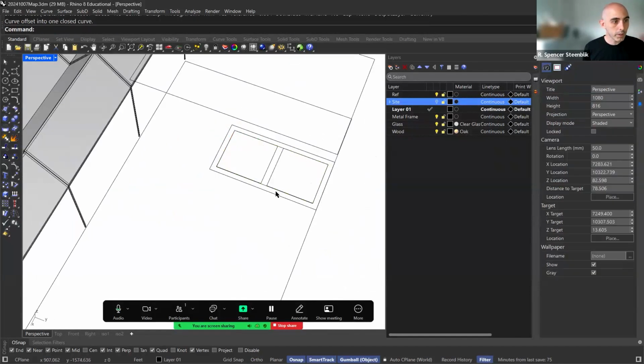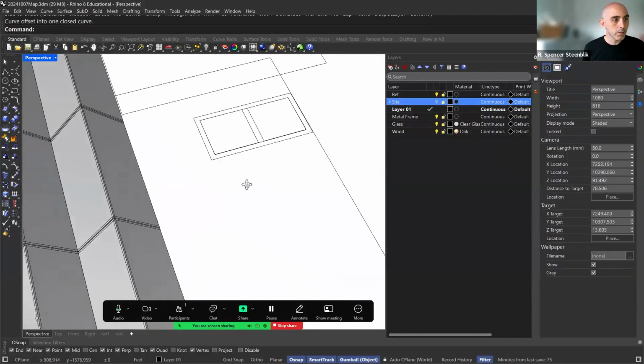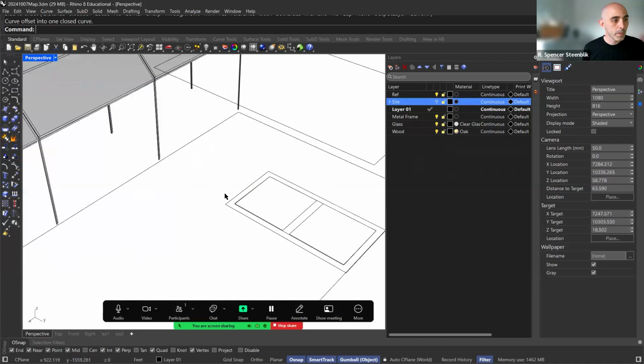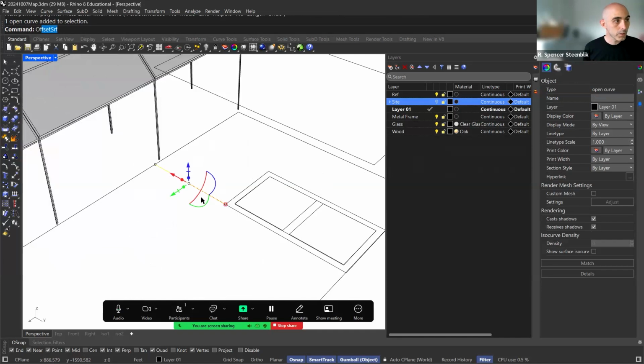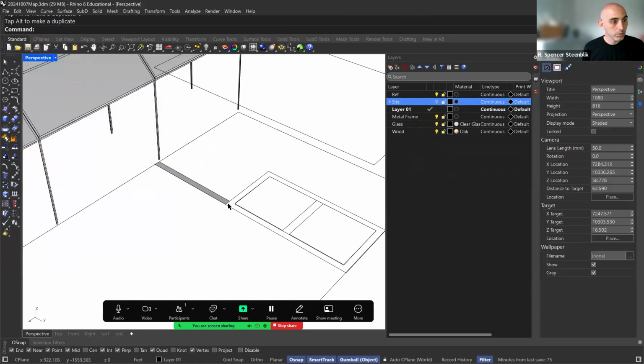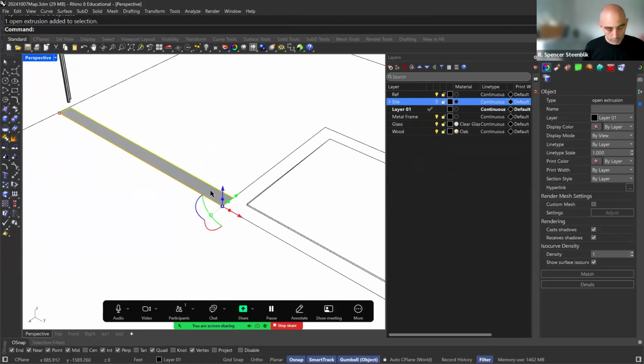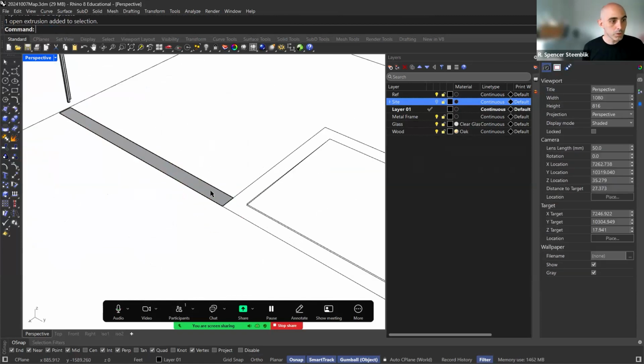So now we have a nice understanding of where those bathrooms reside. Then we'll want to do the same thing here: intersection, offset, or we can even just extrude that 8 inches. That gives us the border. Actually, we can use that.